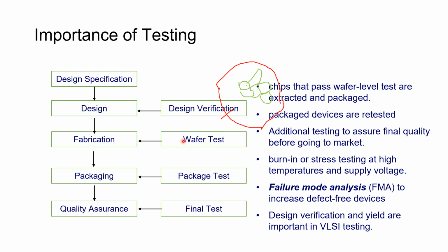So after fabrication, you get the wafer, you test the wafer, you take the good dies after testing, and you package them. Packaging will have these kinds of wires, right? So let's see what is the package. You would have seen it in your labs, right?